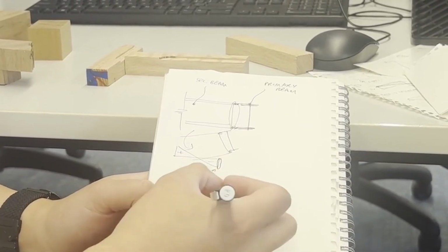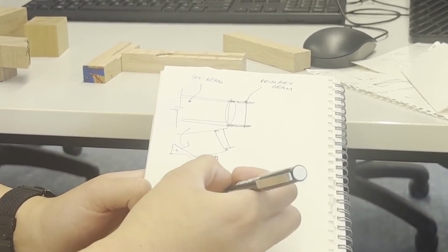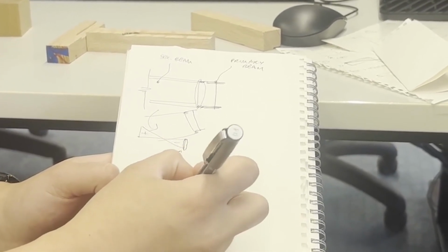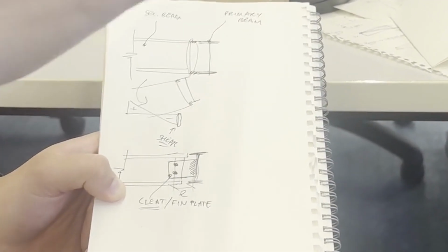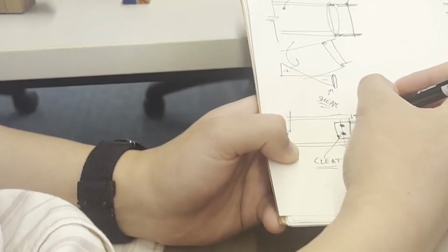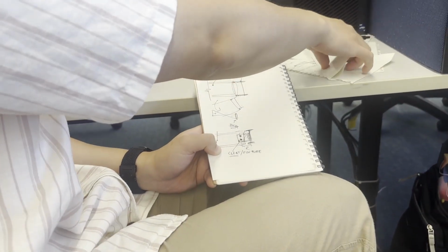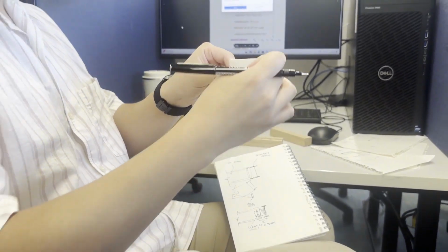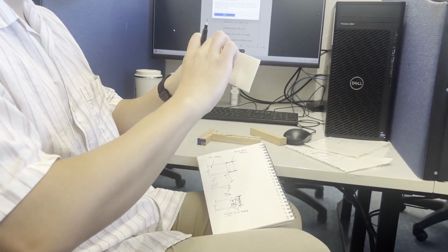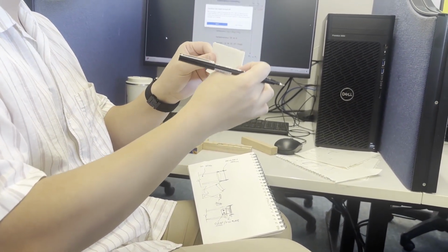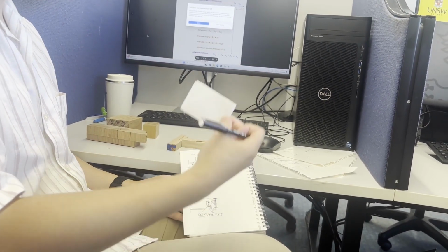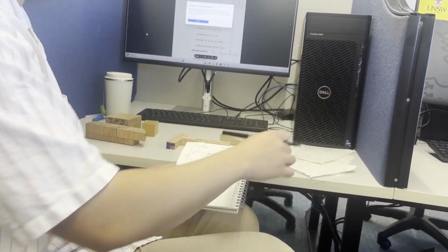So that's one way to do it, and the reason I don't like this way is because there's a large lever arm from here to here. And so you're basically putting this plate into bending, right? It's like these dimensions, and you're basically bending it. So now this weld has to take a lot of bending, and the plate also has to take. Oh, sorry, the bolts also have to take a decent amount of bending.